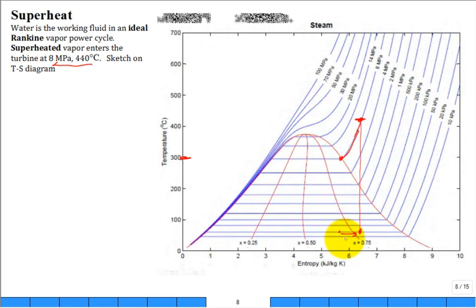It's higher quality. It's not going to be a practical issue of having a low quality steam at the exit of our turbine, which is poor for performance. Did I mention why? As a practical issue, the steam exiting your turbine needs to be fairly high quality. Okay, it didn't. So what again is the quality? It's a mass fraction. So if it's high, it's all vapor. If it's lower, I'm getting liquid.